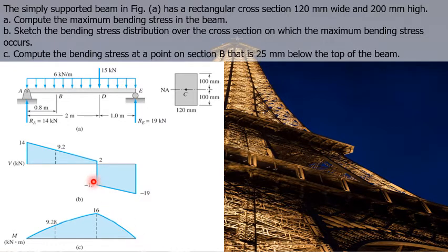Again, this linear curve in shear becomes a parabolic curve in the moment diagram. But does it concave upward or downward? Again, at point D, the parabolic curve should have a zero slope. And at point E, the parabolic curve should have a negative slope. And for that to be possible, this parabolic curve should concave downward. Again, we went back to 0. That means that our moment diagram is correct. We went from 0 to 0.